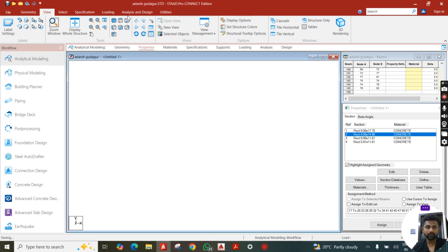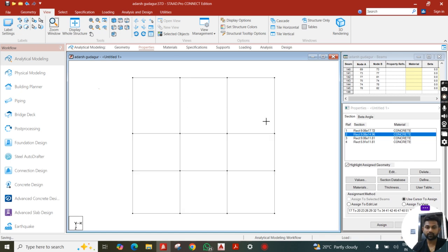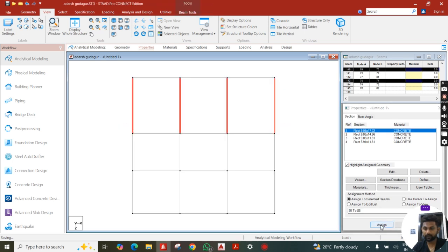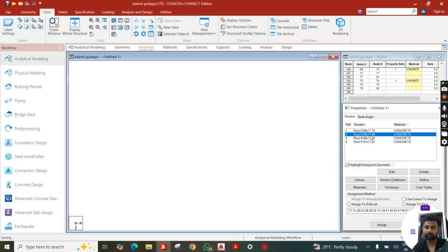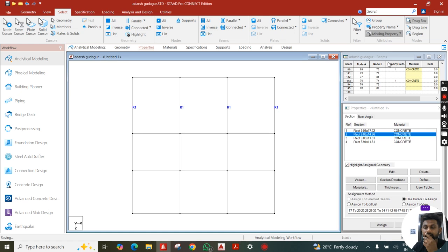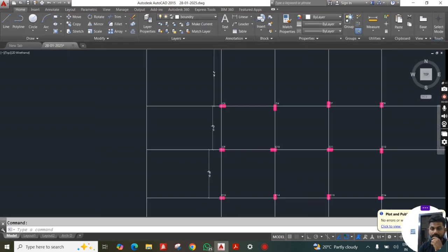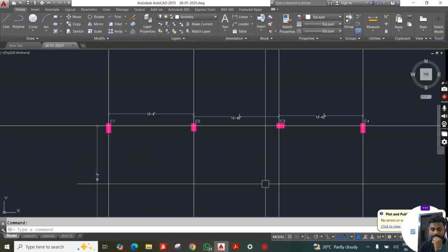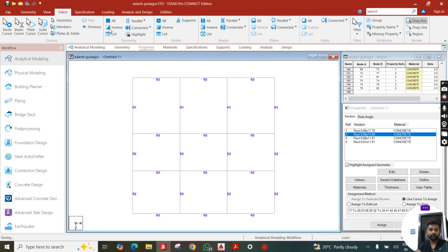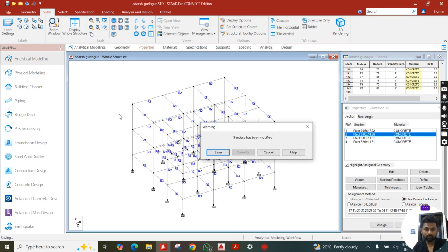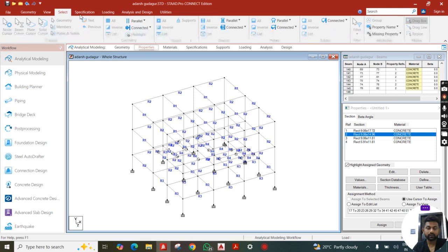We are going on terrace. Same thing. This 18 beam, because the span is huge, so I'm thinking of giving it 18. All these others I'll give 15. What is the distance between this? 13, 13, 13. Fine. Okay. So we have given the material properties.